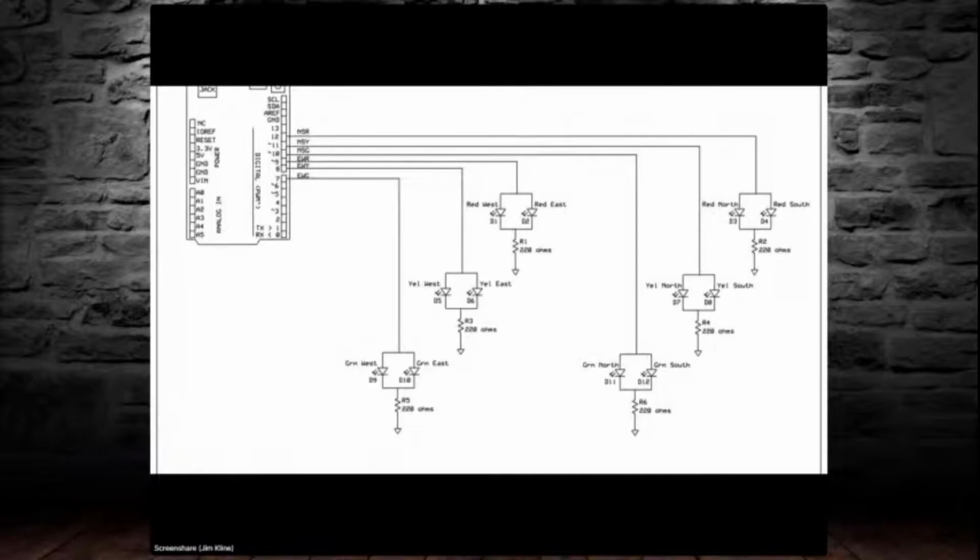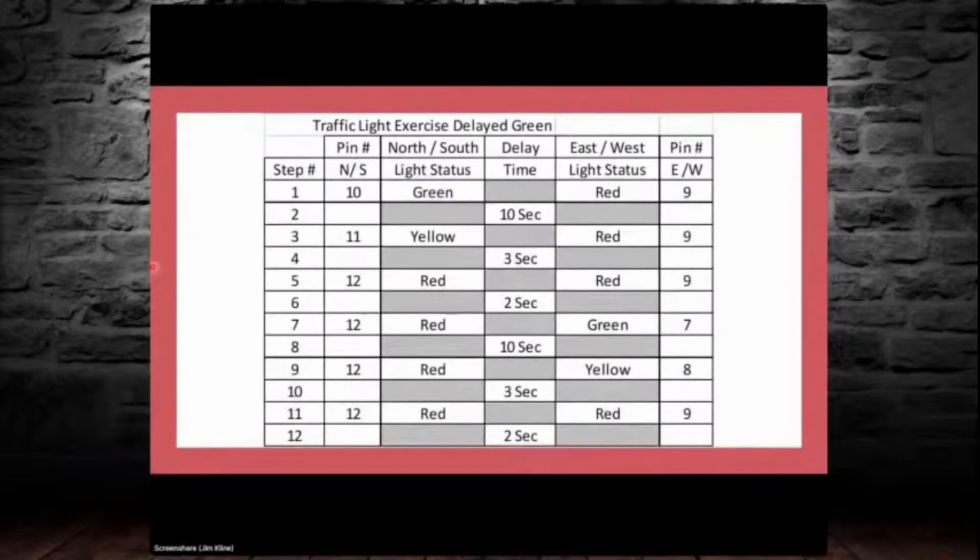One other thing to note is these labels here for the wiring to the individual pairs of LEDs. And notice how this drawing is nice and clean. The wires to the various LEDs go straight across, no crossovers. So we used a schematic of the Arduino to identify the 6 Arduino pins that will control the on-off conditions for each of the lights. We also labeled each of the pins to help us remember what each pin is controlling.